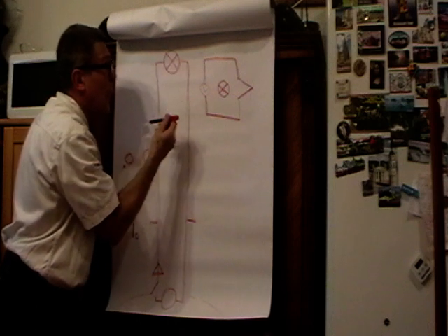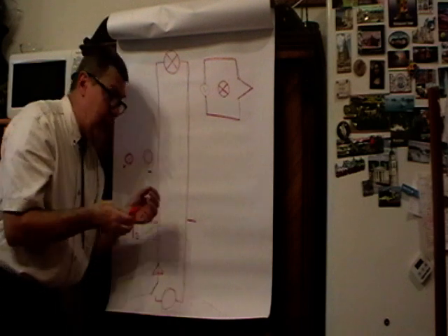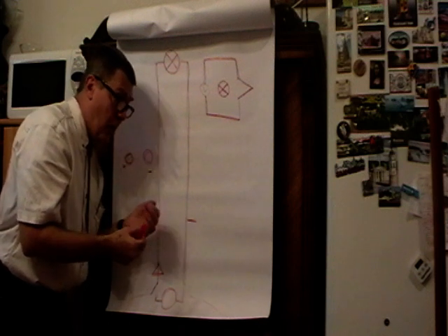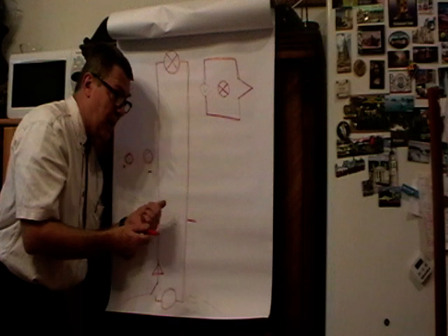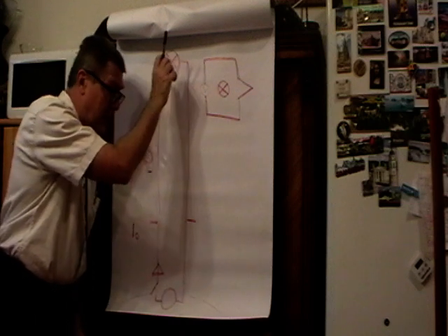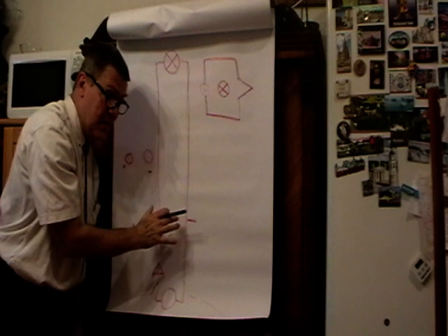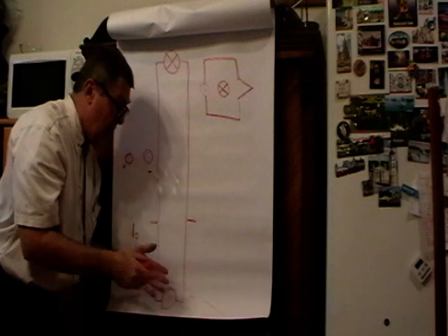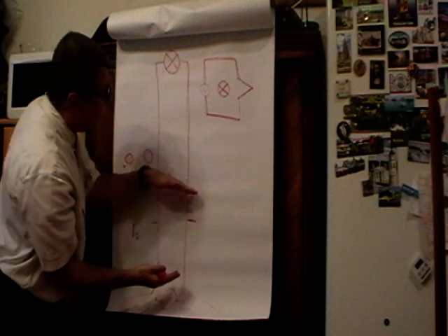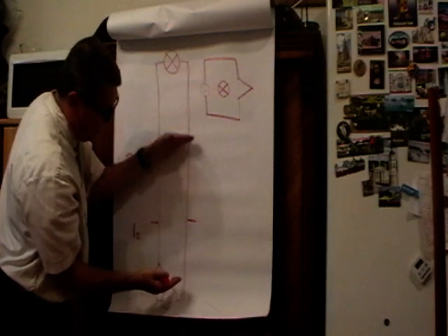So what would happen is that, and I will tell it two ways, the wave reflects. It reflects from a short, so it reflects anti-phase. That is, a wave of minus V voltage would be reflected. Or we can say, okay, the information, like with a radar, we have sent a wave, it touched the target, it returns back.